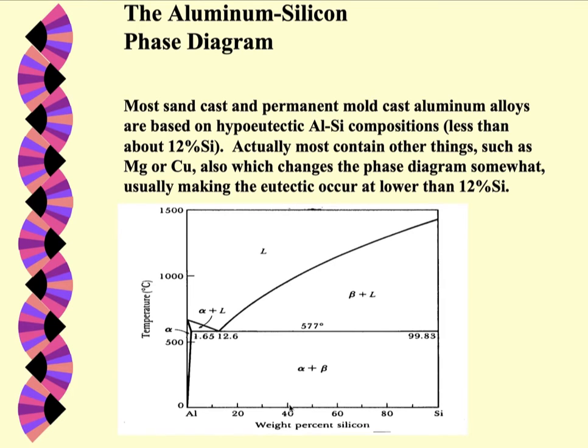You see, if I had 40% silicon, this is going to be 1,000 degrees C that would melt. Okay? And then if I'm down here, it's just 600 degrees C. So you can see that the temperature at which it melts is determined by what the composition is. There might be other elements in here though, and you can't really account for the silicon and magnesium and the copper. Otherwise the phase diagram gets to be like 5D, and there's no such thing.